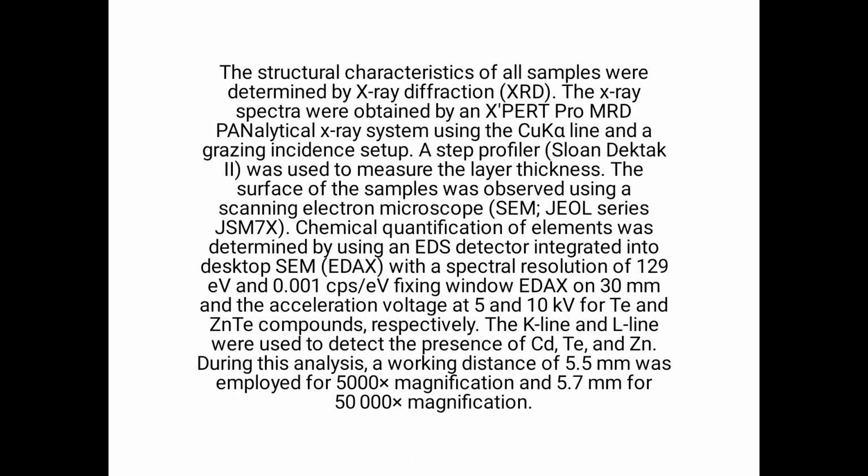FTO/CdS/CdTe/ZnTe and FTO/CdS/CdTe heterostructures were obtained, and metallic Cu contacts with a thickness of 20 nm and 100 nm respectively were deposited over a 0.078 cm² area. The structural characteristics of all samples were determined by XRD. The full form of XRD is X-ray diffraction.